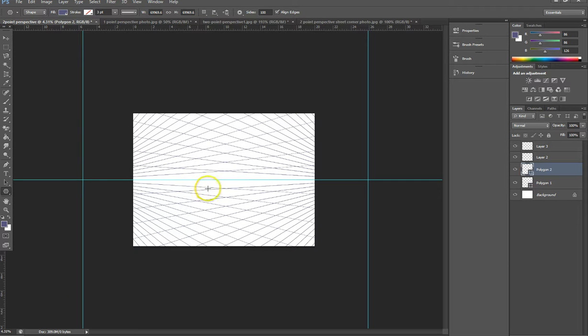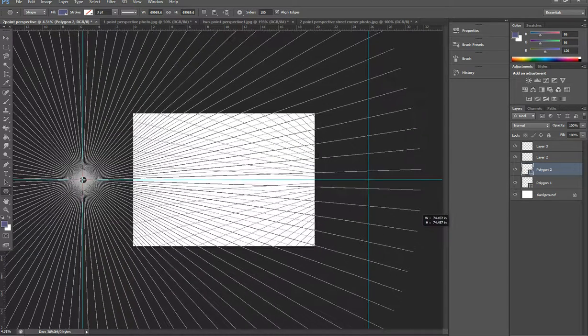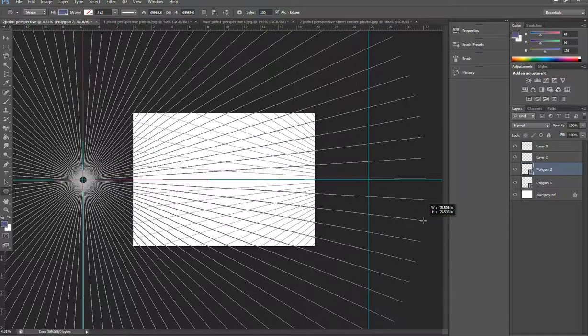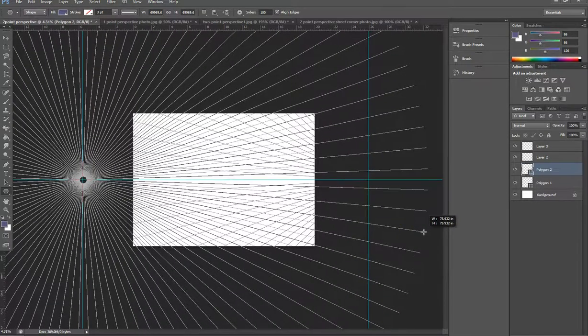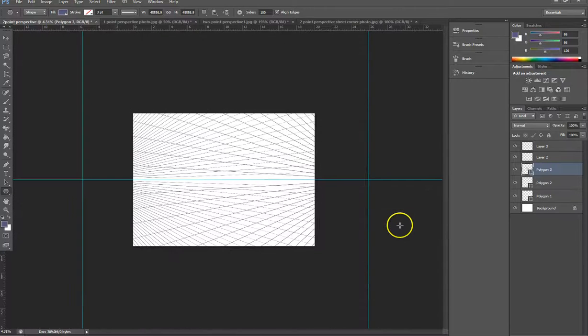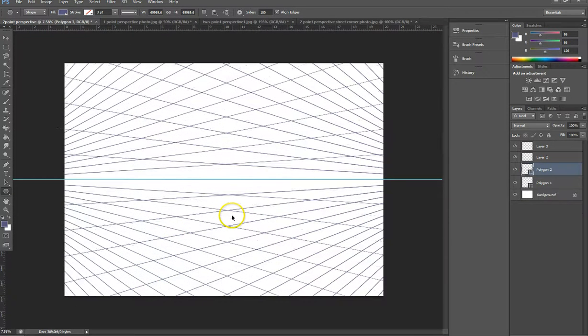If you find that this grid is not intricate enough for you, the nice thing is that we can go back here in the exact same place where the vanishing point is, and you can place them. So this is where it is currently. You can rotate it slightly, and you can place it between the two sets of grid lines. So you can see if I zoom in closer, it's a lot more intricate, but I don't want it in this case.